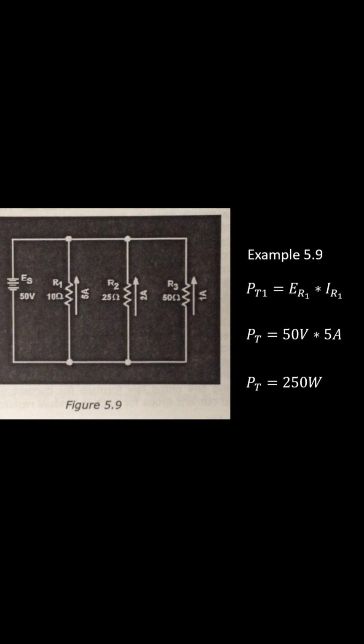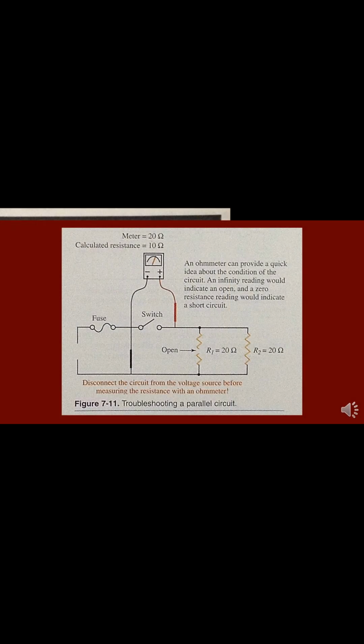Troubleshooting in this type of circuit, figure 5.9, is best done with power off. It is a resistance check, or what most electronic specialists call a cold check. You are simply checking to see if any of the resistors are open. You can also do a current check on each line because an open resistor will show no current. A voltage check will not help you in this case because each line is already reading source voltage.